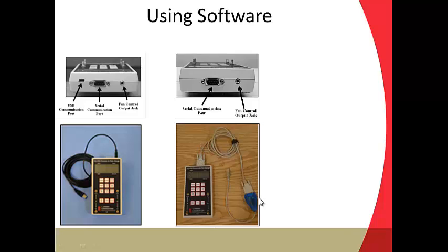It needs to be a straight through cable. And those are available in 6 or 15 or 25 or 50 or 100-foot lengths. So you can buy them with the ends on at various lengths, and they're readily available. And then you'll need a serial. Most computers don't have 9-pin serial communication ports, so you'll likely need a serial to USB adapter.